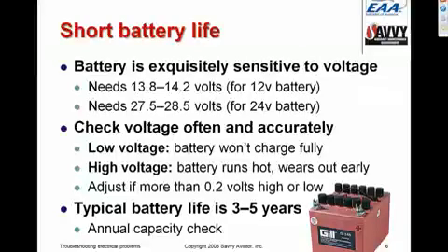And if the bus voltage gets off of the specified voltage by more than a couple of tenths of a volt, particularly if it's on the high side, it's worthwhile to have the regulator adjusted to get the voltage right on spec. Adjusting the regulator is normally a very simple procedure. It's just a screwdriver adjustment on most regulators. Even on my twin, where there are dual regulators and you have to parallel them, the whole procedure takes less than 30 minutes. And for single engine airplanes with a single regulator, it's usually a lot quicker than that.